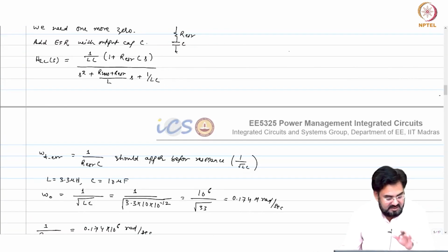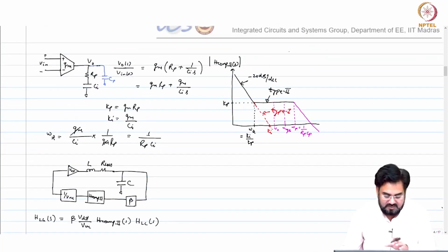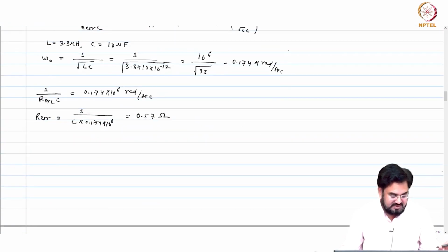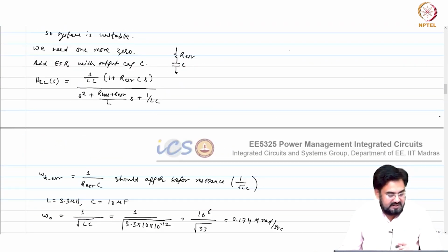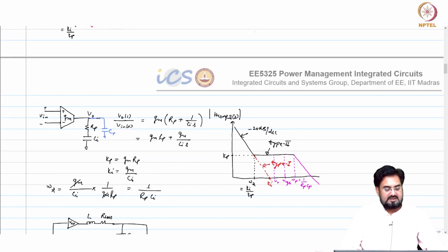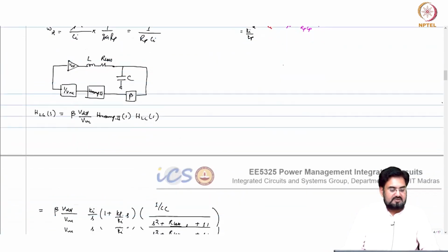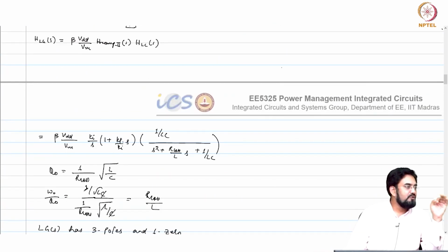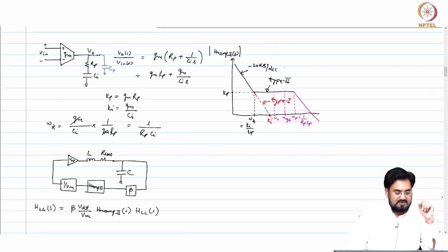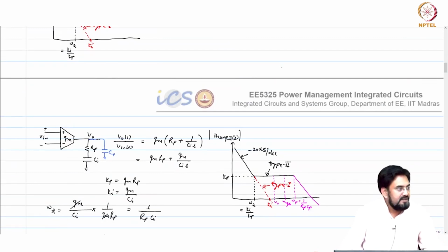Okay, so that capacitor will be there. We have to add that cap to suppress the ripple. If you don't do that, then you may have some noise concerns, and we'll talk about that later. So now in the loop gain, if I want to find the value of these components RP, CP, CI, everything, how do I do that? So first thing you need to know where I want to place the 0. Okay. So once we place the 0, you can find the value of RP and CI.